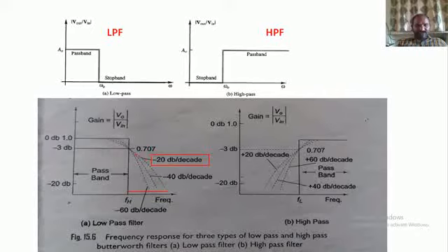So this particular dotted line, whatever dots we have, is indicating the first order low pass filter response. If you go through any textbook and they are trying to indicate the information in terms of the decibel, then this reduction means the gain after cutoff frequency, the gain of this particular circuit is reduced by 20 decibels for every 10 times the input signal frequency variation. For every 10 times the input signal frequency variation, the gain is reduced by 20 decibel. Okay, now if you see this, again so many components are accepted by the low pass filter.